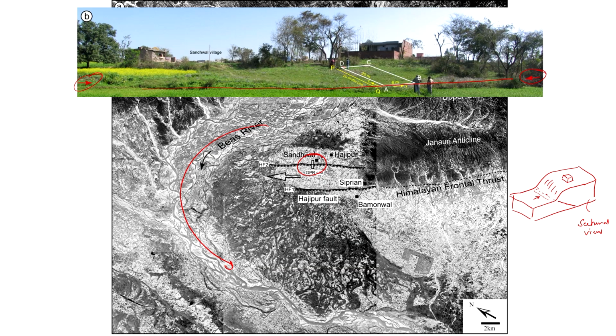It is dangerous in that sense, because a trench can collapse, plus you cannot keep digging across the fault scarp. So, you need to be very precise, because you need to go deeper at the place where you have the fault. For example, if we were talking about here, we need to go deeper at this location, because that will give us the information of more number of events preserved in the stratigraphy.